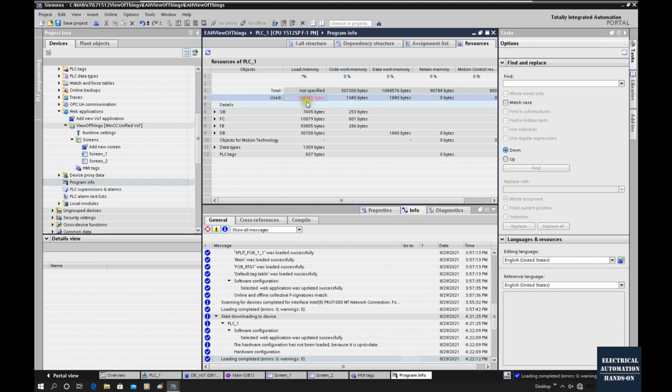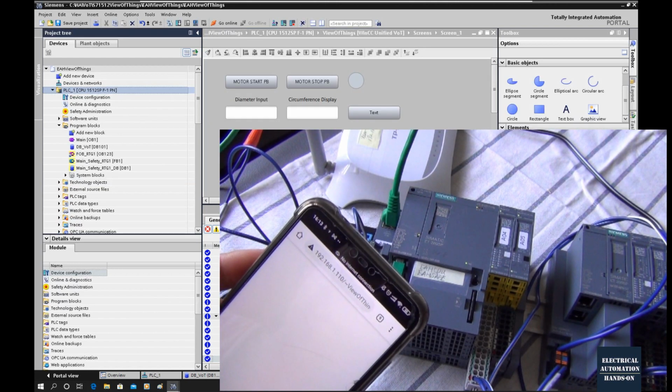Regarding the S7-1500 PLC, the load memory is the SMC memory card. So you need to take care of the memory card size you are selecting and using. Here we can see it takes almost 150K bytes already. So keep in mind, the bigger the screens and the more components in the screens, the higher the size cost for our load memory.